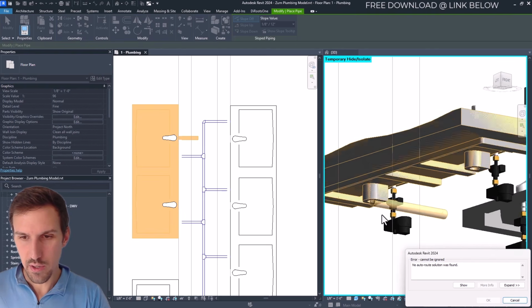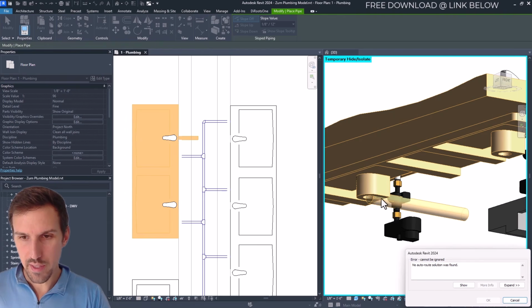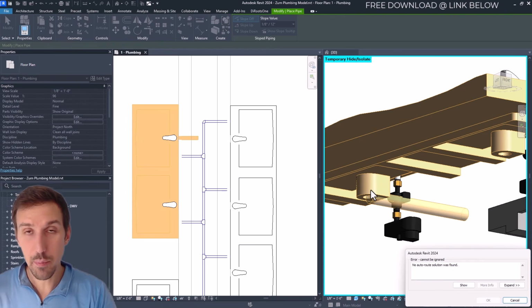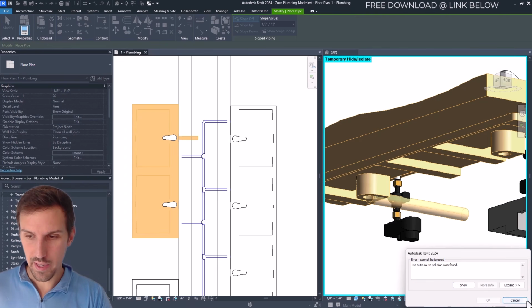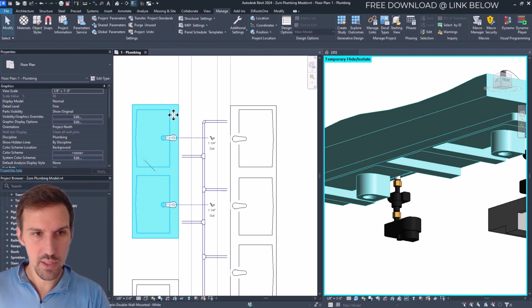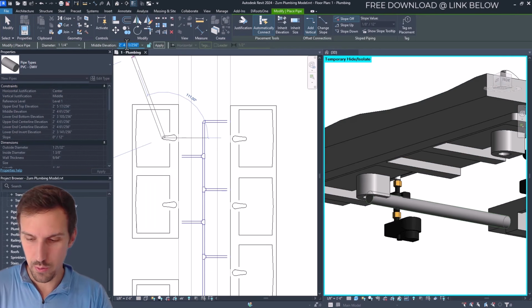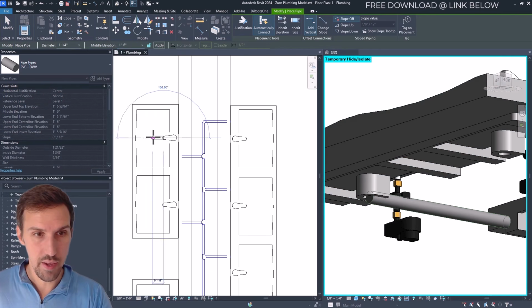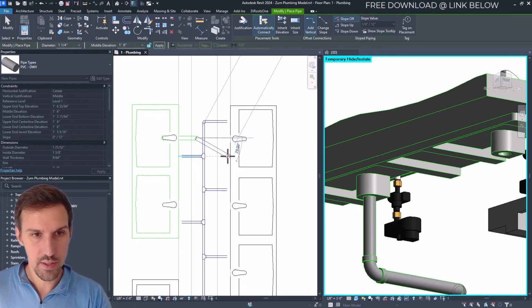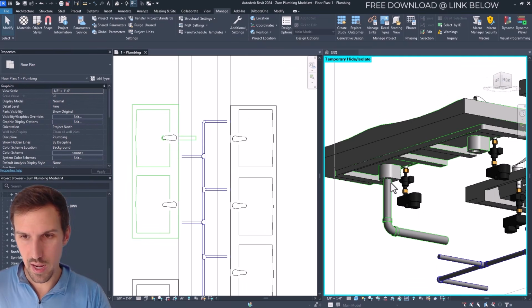That's because when we were creating this pipe, we didn't drop it down enough to be able to fit an elbow. So we need to do that first. I'm going to hit cancel there. And this time, let's drop it down. Let's click on our pipe button, and drop it down to 1'6" by changing the elevation and then clicking into the view right here. And look, this time we dropped it down and it created a nice elbow.